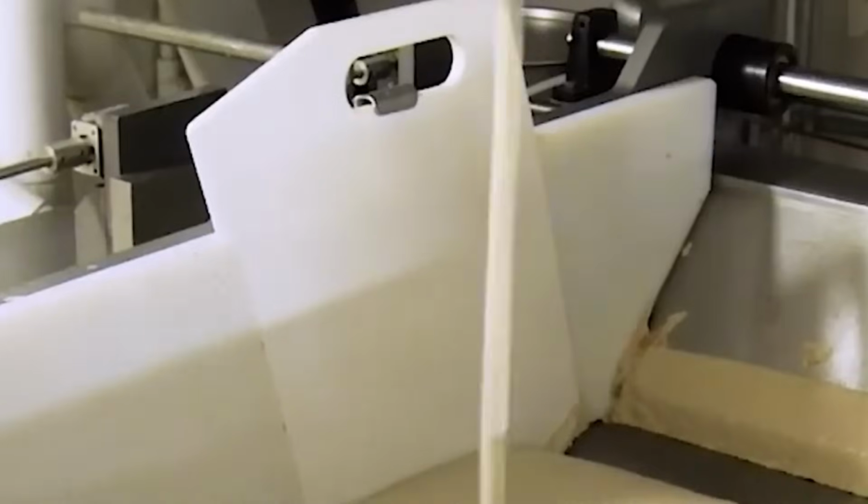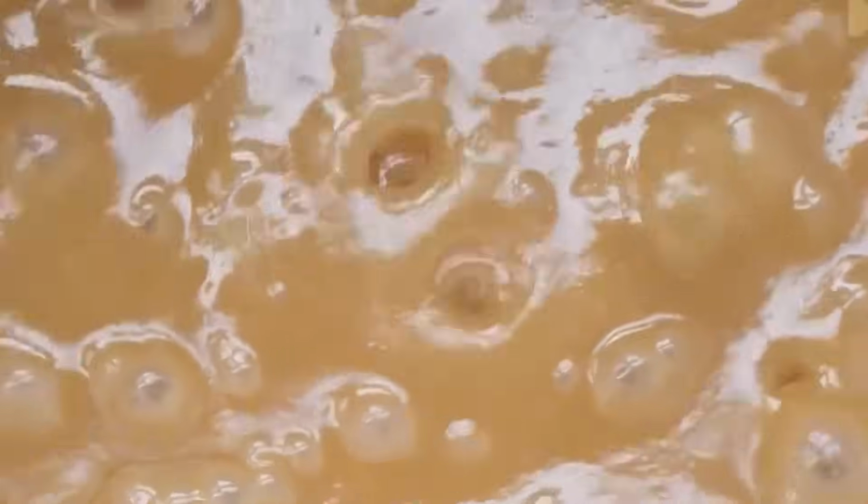Pallets are wrapped with stretch film and labeled with pallet license plates that include batch number, product code, production line, and timestamp. Finished pallets are stored in temperature-controlled warehousing environments between 18-20 degrees C and 50-60% RH. Warehouse management systems, WMS, use barcode scanning to log pallet locations and ensure FIFO inventory management. Distribution occurs through cold chain logistics to ensure product quality during transportation.